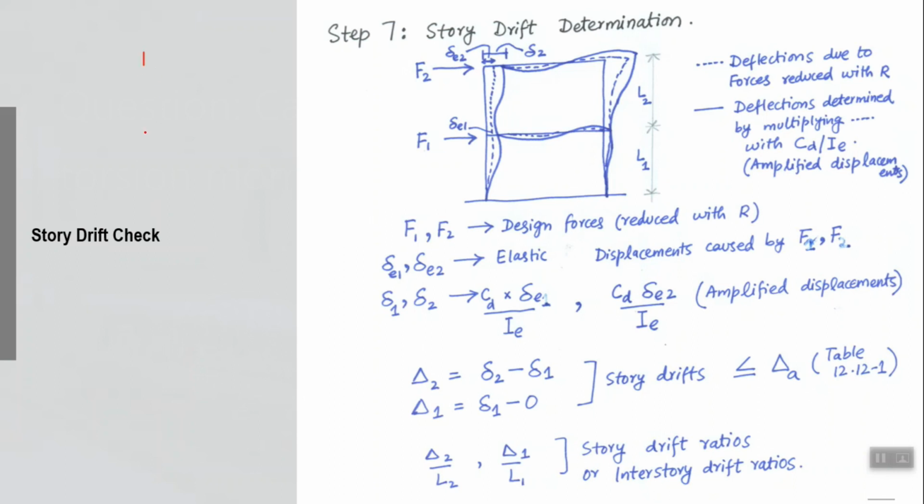What we did is actually that this is the level of force, elastic force, which the design level earthquake is going to produce. If we provide enough capacity for the structure to remain linear up till this level VE, the structure will follow this line and the resulting deformation will obviously be this one.